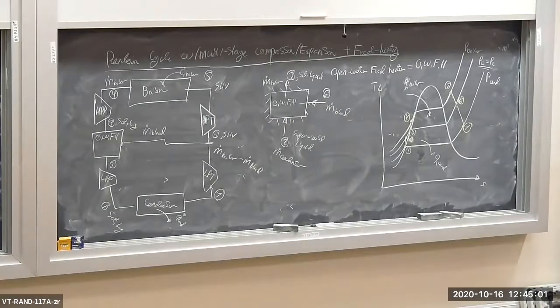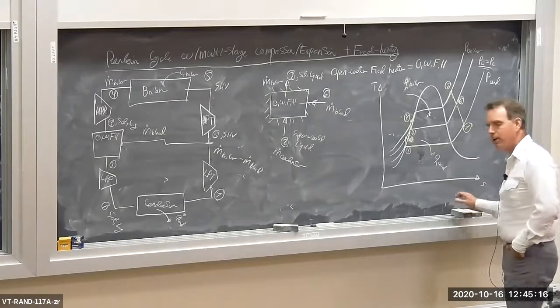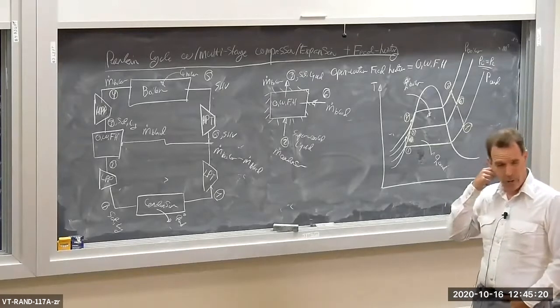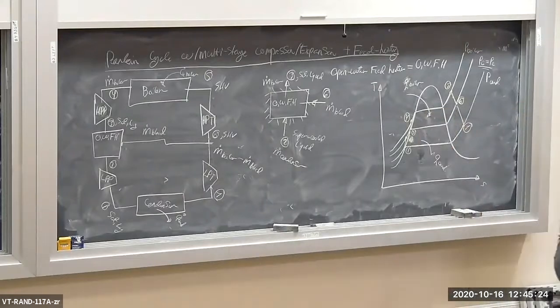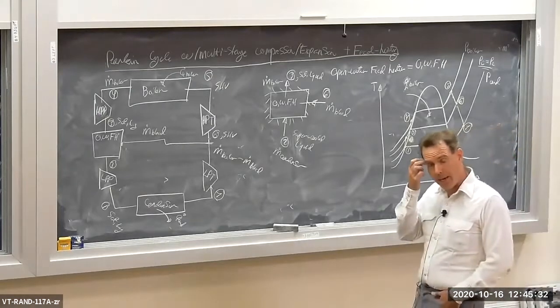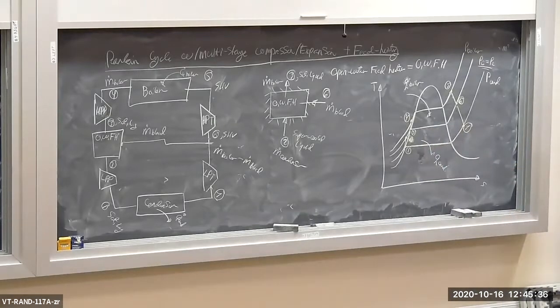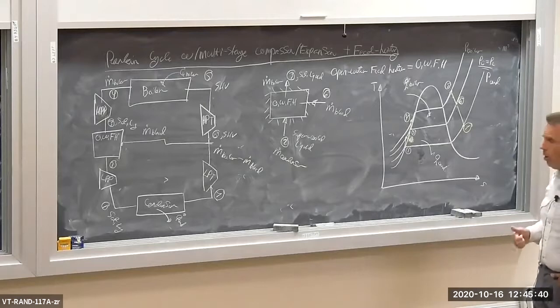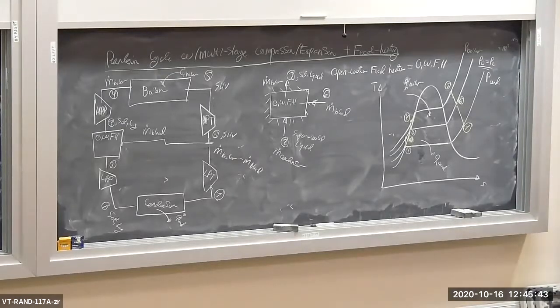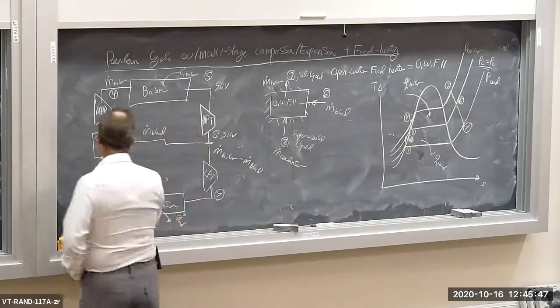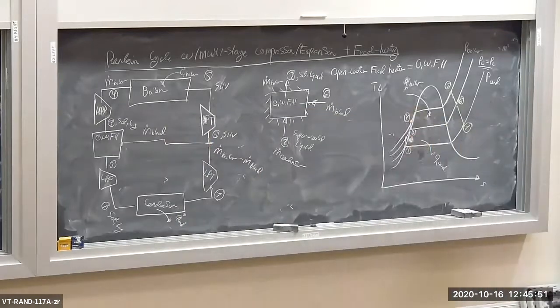The Brayton cycle example that we did previously, a lot of the heat rejected in the atmosphere could be reharvested or regenerated, and if you go back and look at the example with regeneration in the Brayton cycle, we had a significant increase in efficiency of the cycle. As I recall, without regeneration, the thermal efficiency was about 25%, and with regeneration, with a regenerator efficiency of about 80%, the thermal efficiency of the Brayton power plant gas turbine went up to like 46%. With these open water feed heaters here, you're lucky to get a 1, 2, maybe a 3% increase in efficiency of your overall Rankine cycle.